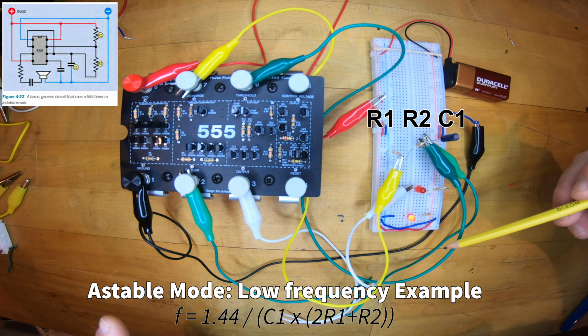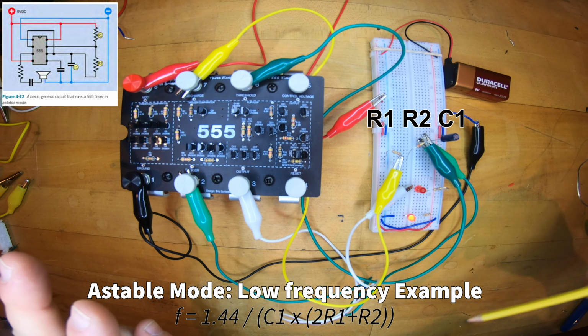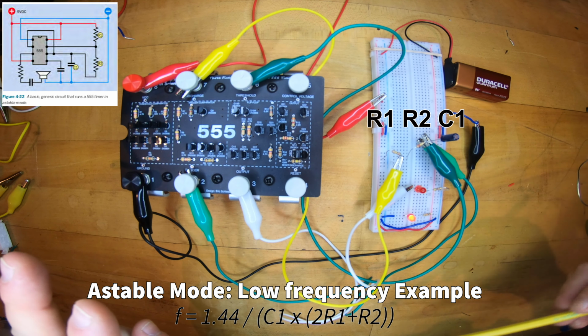I've got two wires coming off R2, one to the threshold and the second one to the trigger, because those are going to be firing at the same time. And then the output is on a white cable, and I have it going just through an LED and resistor. Now this is different than what is shown in figure 4-22 in the textbook. They don't do a blinking LED, but I would like you to do one first in the circuit. You have to choose R1, R2, and C1 appropriately. I've purposely made sure you can't just cheat by looking at my video.